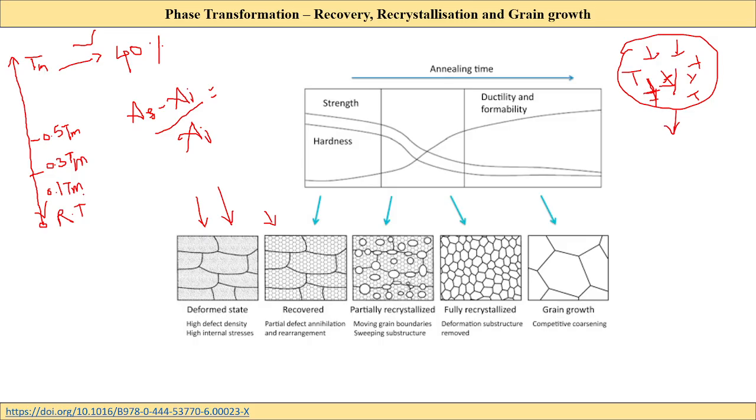So what's happening is, because I am supplying a certain amount of energy as heat energy, that means I am giving atoms the ability to move. Dislocations are nothing but extra half planes, so they are also atoms, right? Now because of the increase in energy of the system, these dislocations will arrange themselves in a certain manner as an array of dislocations, right?